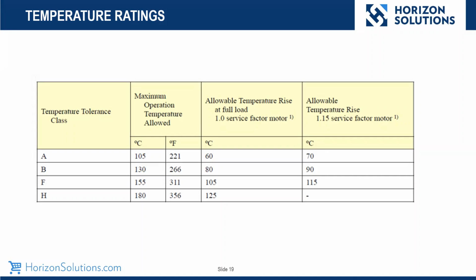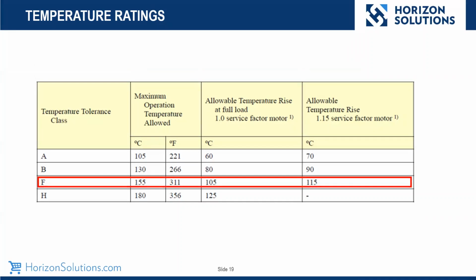the insulation rating. So what we've got is different alphabetical ratings for these temperature ratings to withstand more heat and not melt down and cause shorting inside the windings. So we basically say, especially with VFDs, we prefer an F rating or above.